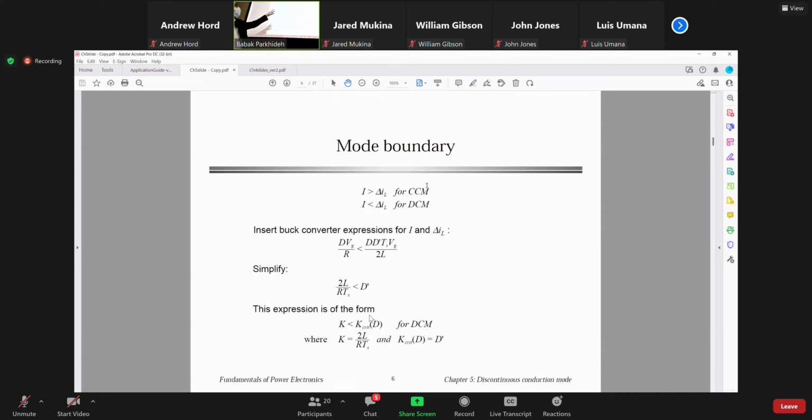So for a simple buck converter, the load current is the average value of the inductor current. So you have output voltage divided by R, nothing else than D Vg over R. You assume the converter operates in BCM, boundary conduction, so you can use all the CCM relationships.